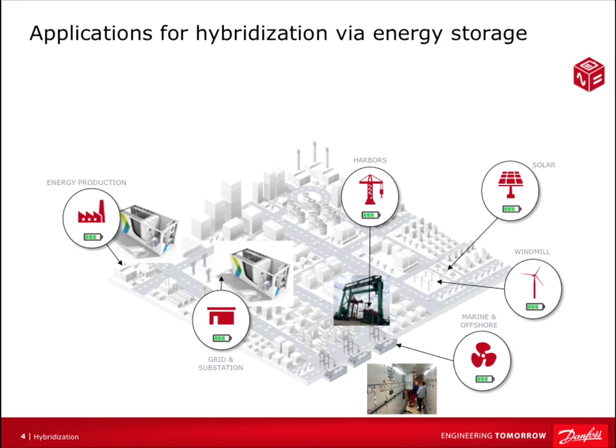That can be from a battery supplementing the main diesel genset, rather than oversizing the diesel genset to operate at a point where it's no longer as efficient. And then when lowering the load, now you can recover that potential energy that you would have normally bled off through resistors and heat, becoming inefficiency. So now you can optimize your overall efficiency in this particular application.